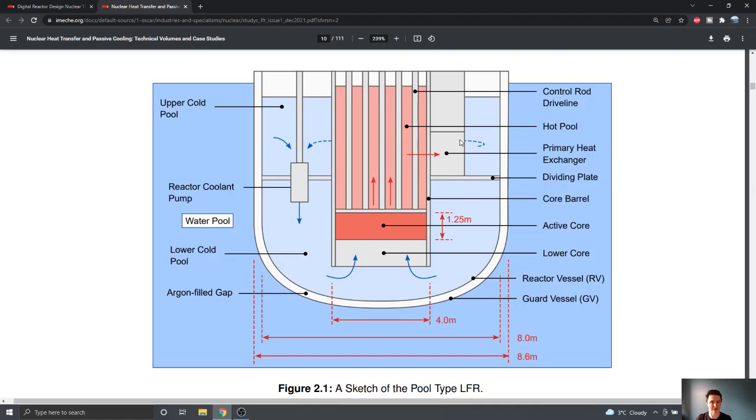But back to the primary coolant. What we're interested in is that once our coolant leaves the heat exchanger, it's now cooled down. A lot of the heat that it absorbed from the core has now been given off to the secondary coolant. The primary coolant is then going to be driven down. I've got this dotted line round the back to show that this is a circumferential large pool around the outside of the reactor. And that coolant is then going to be drawn into a pump, just like a standard pump, but this one is driving the fluid back down from the top of the reactor, back underneath into the bottom of the core again. So you can see that this entire circuit creates a complete loop.